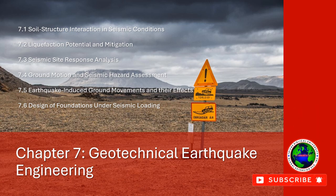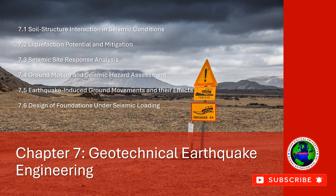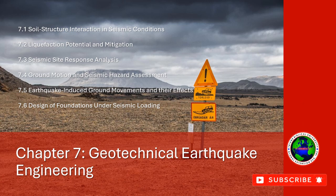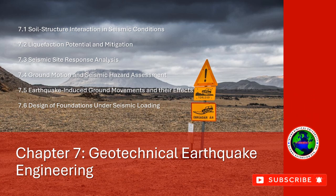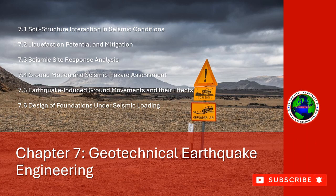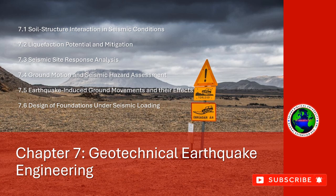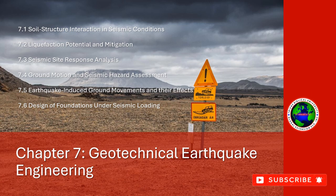Methods for SSI analysis: linear elastic methods for simple analysis of soil structure interaction; nonlinear dynamic methods for more complex assessments, particularly for sites with soft or liquefiable soils; and use of finite element analysis, FEA, and boundary element methods, BEM, for detailed simulations of the seismic response of the foundation and soil system.